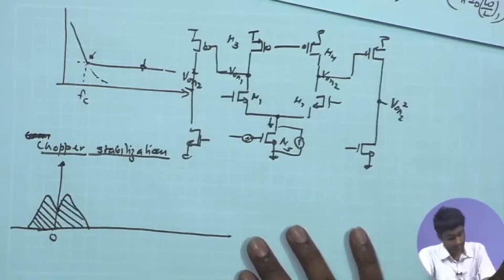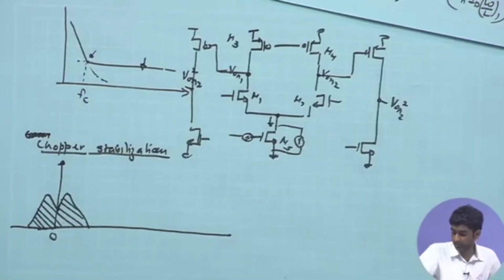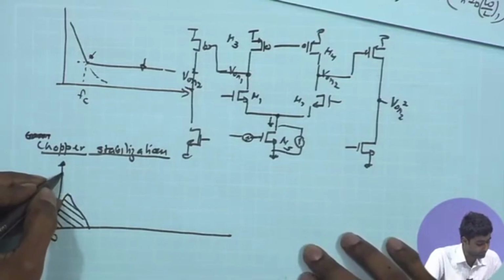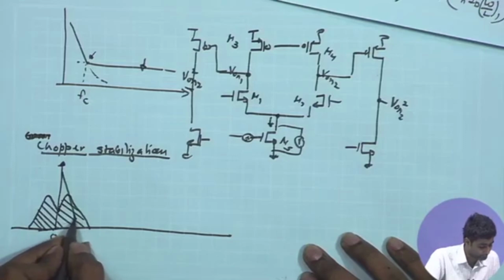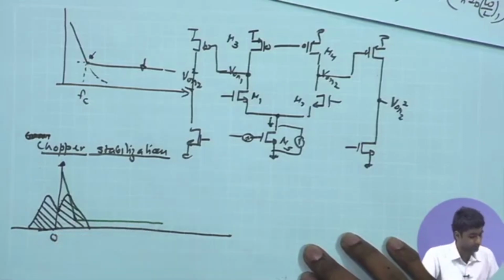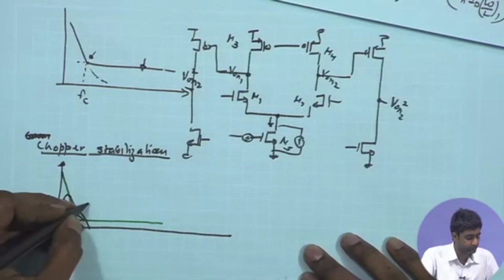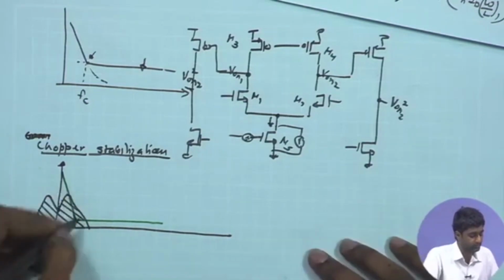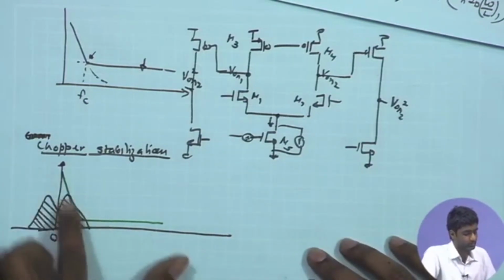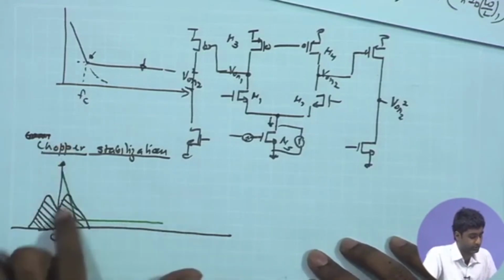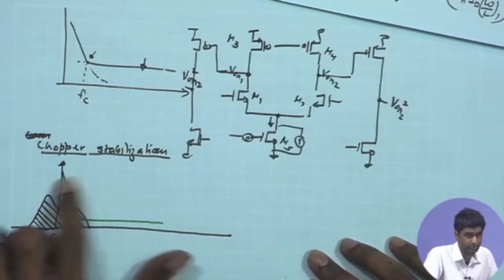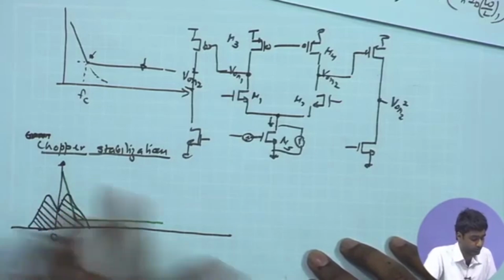Under this condition, I also have the 1/f noise, which can very sharply overlap with this, even if you are designing very carefully, trying to push the 1/f noise further and further. We said that up to 10 hertz it may be feasible, but beyond that it becomes difficult. So, definitely we would like to save our signals from this increasing 1/f noise, which can significantly corrupt or completely destroy our signal content, at least that which is closer to lower frequencies, closer to DC.